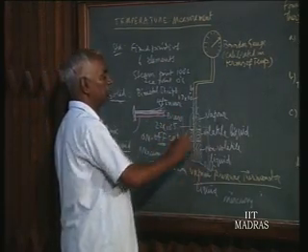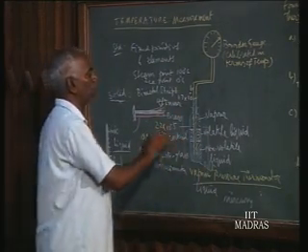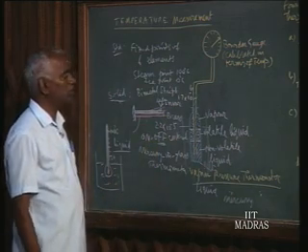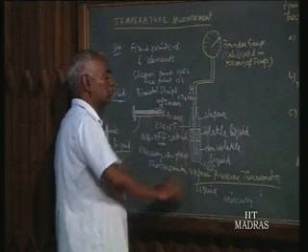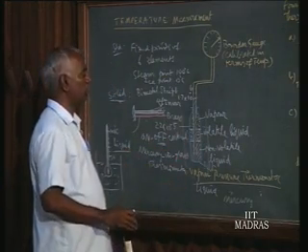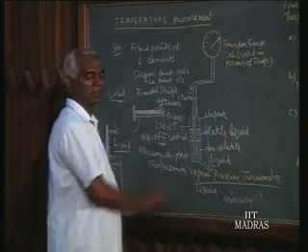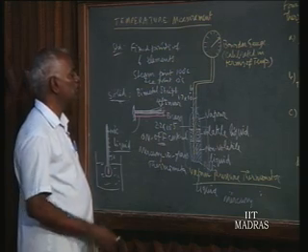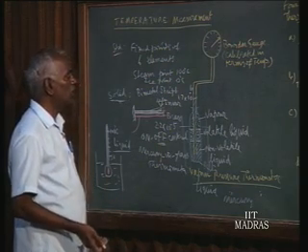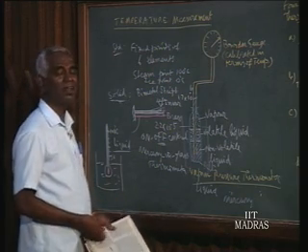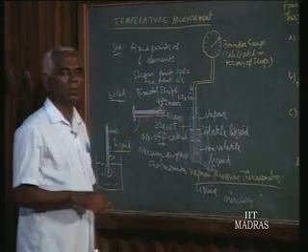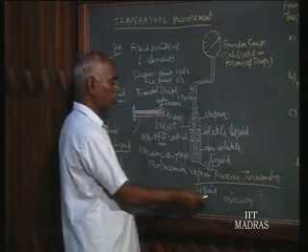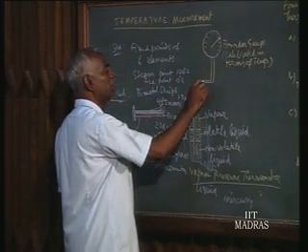Now when it is immersed, the liquid tries to expand, but it is not allowed to expand because it's a constant volume. So to the extent of the expansion, compression occurs, and it develops pressure. Since it's a constant volume, since there is no room for expansion, that much expansion results in a high pressure of the liquid. That pressure is read in the Bourdon gauge again. But the problem in such a liquid pressure thermometer is any intermediate temperature.